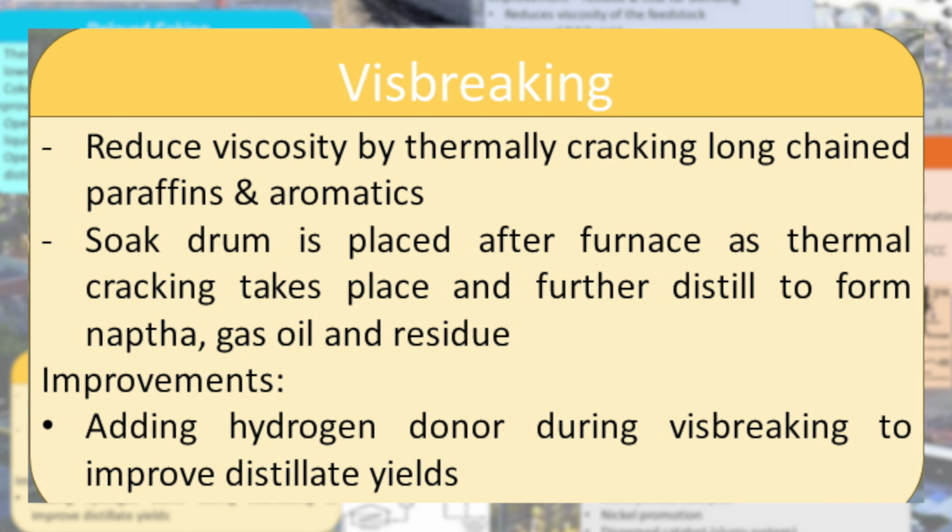Hydrogen donor supplies the hydrogen necessary to obtain good distillates by hydrogenating the thermally cracked oils. For example, tetralin acts as a hydrogen donor, reduces coke formation as well as producing a product of reduced viscosity, pour point, and sedimentation characteristics. The process gives substantially higher conversion of residue fuel oil to gas oil and higher products than conventional visbreaking.